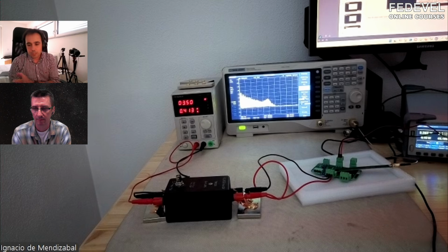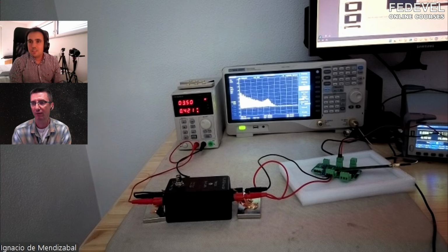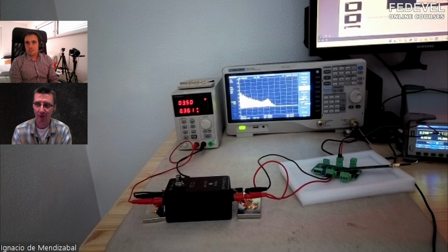one priority is to reduce frequency, but the real factor that makes an impact on EMC is the rise time and the fall time. Because if it's faster, then also the edge has to be faster. Not necessarily. But for example, even for standard signals like digital signals, if you would like to have faster communication, you would like to use a faster signal, then the edges need to be a little bit sharper.